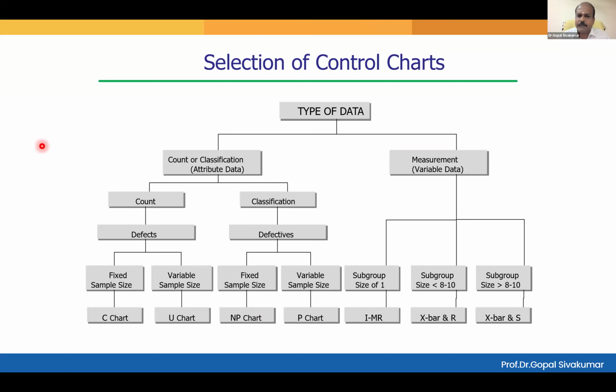Which control chart should you go for? You are worried about the number of defects they are making, right? Every day, how many defects or how many errors do they make? Will you go for the attribute chart or a variable chart? Variable means measurable. That will have a unit of measurement. You are now counting how many errors.